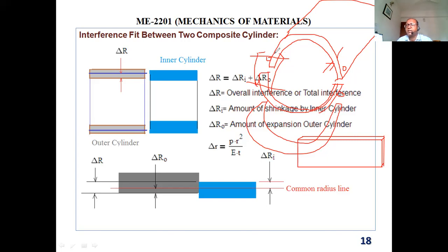Okay, it is difficult because it's a curved surface. Then you need to make a hole, and you have to make a special jig and fixture to hold the parts on the machine table. Okay, so after bringing the parts, after 1.5 months, we checked the radius. Then we saw the radius had increased.